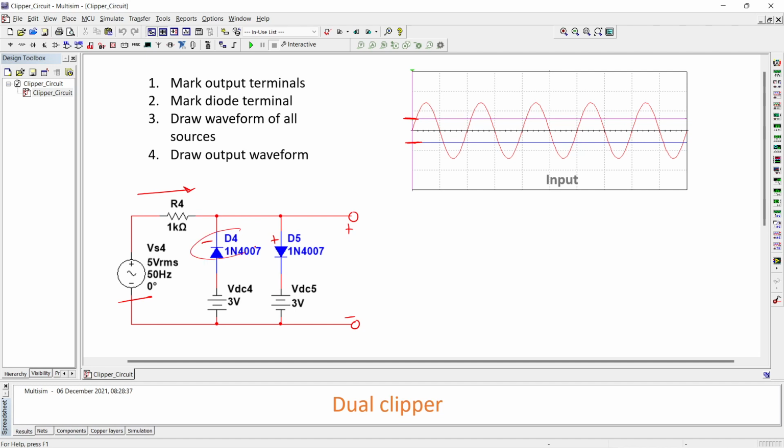First diode comes, that is D4, and the negative terminal of this D4 diode is facing towards the positive. That means this section of the signal we should remove, because this is the line of this battery. So this section we should remove. Now after removing this section, at this point we have only this much of waveform, right?